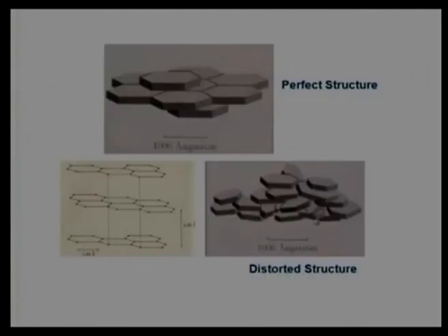This is a typical microstructure shown of the carbon, of graphite. It says that if they are in perfect structure, they can sustain load, but if the load is increased beyond their capacity, as mentioned in the previous slide, 275 megapascal stress, then they get distorted, they get damaged. So the beauty of the lamellar structure is removed in that situation. It will no longer be a lamellar structure, it will be a distorted structure.